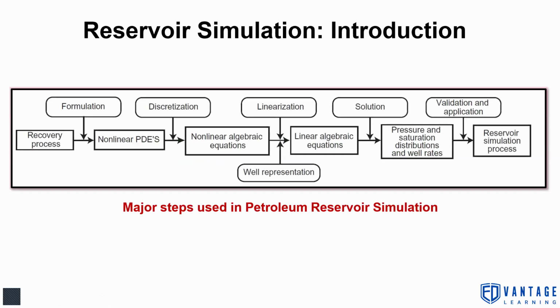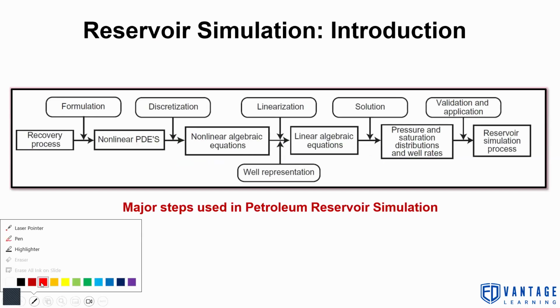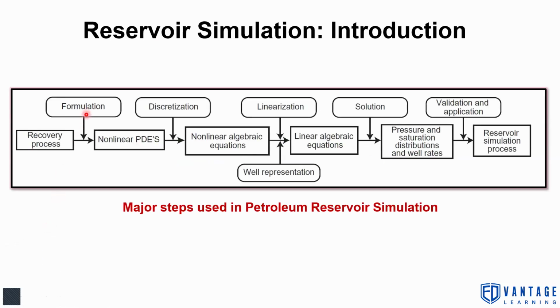So simulation has several steps where we try to understand the recovery process, and we formulate the recovery process with several equations, which come out to be nonlinear partial differential equations. We discretize that to make it into algebraic equations. We represent wells and we linearize them. So wells are generally internal boundaries. So we linearize that to linear algebraic equations, and we have a solution for these linear algebraic equations, which gives us pressure and saturation distributions and well rates. So we validate and apply this. This is the entire simulation process.